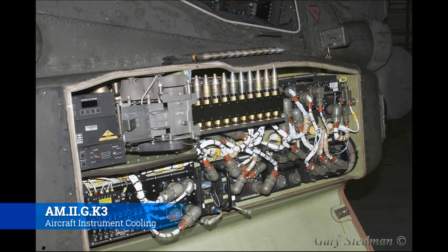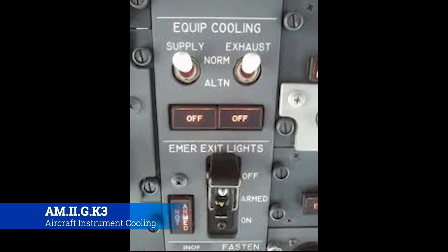And that's all instrument cooling really is: your computers are built to operate at a certain temperature at all times, like room temperature. And then there's a range and there are tolerances like anything else, but really it can only take certain levels of extremes, and if it gets too hot, then you're going to start to have errors. So equipment cooling is absolutely essential to proper operation of any avionics suite that's out there. Now, equipment cooling on your 737 works like this.